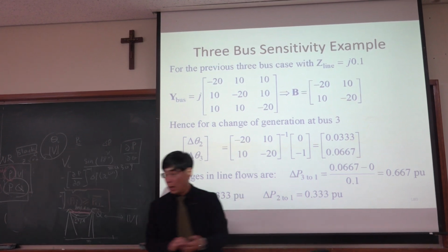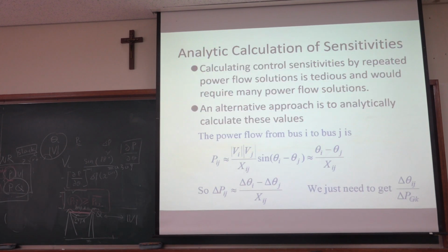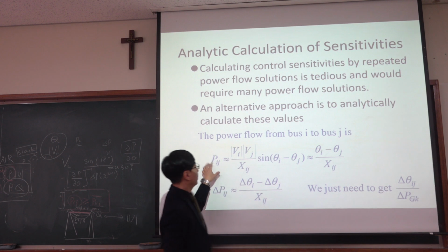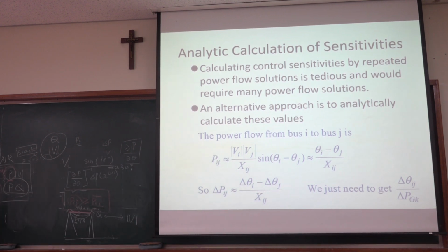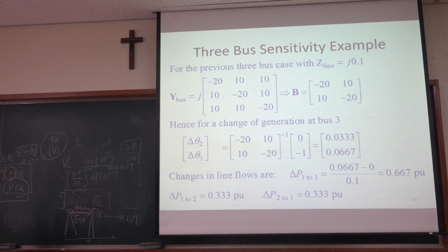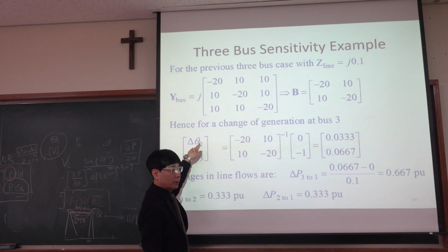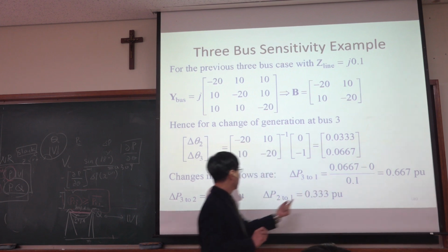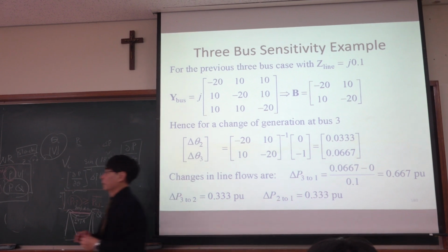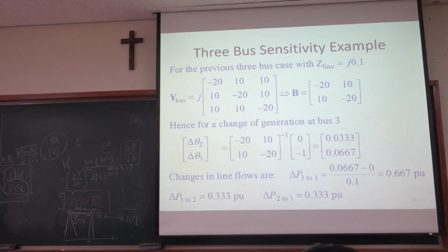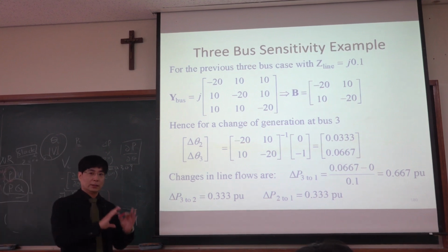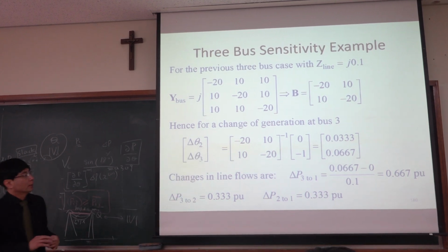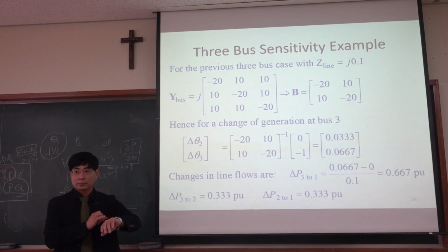Yeah, so our approximated solution, the power is determined from here. So when you compute the angle, from that you can compute the power. So that's this. So using DC power flow, you compute the phase angle, and from that, you can check the increase or decrease of power on each line, 3-1, or 3-2, or 2-1. Okay. Well, and this is about the sensitivity. Not quite clear yet how we can systematically solve the congested line, but anyway, we can use this information. So let me stop here. And next.